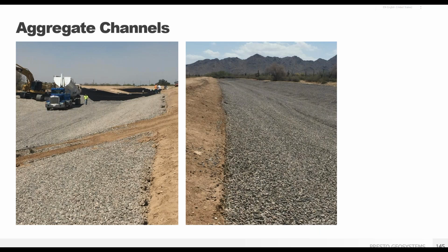The infill was waste rock from a nearby quarry and is not of the greatest quality, but that's all right. When using GeoWeb, the rock does not have any requirements other than size and that it be angular, so money can be saved on material and hauling costs. The only infill material to avoid is river rock and rounded stone, since it does not lock up and will be scoured away over time.